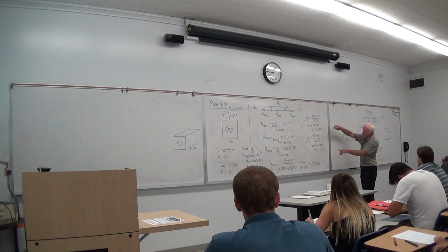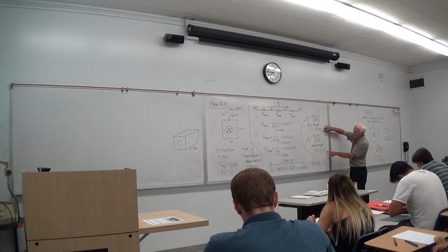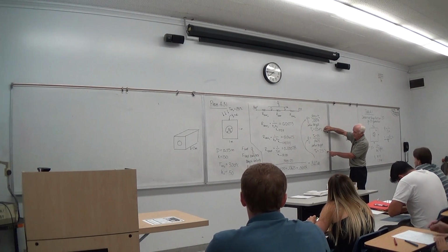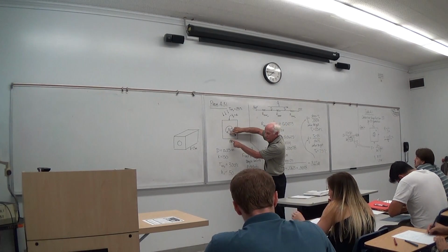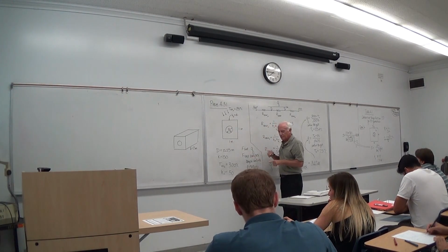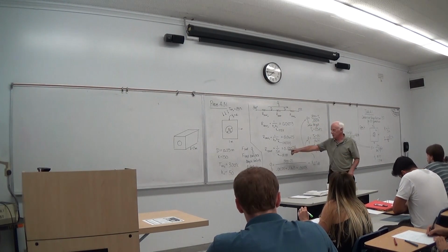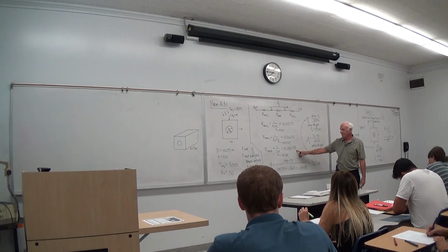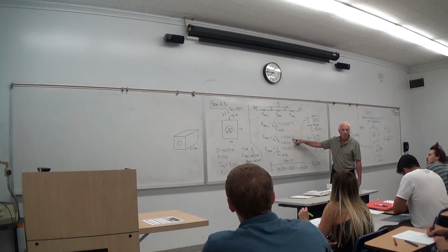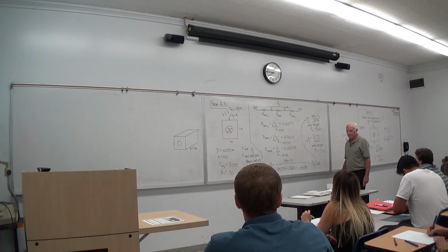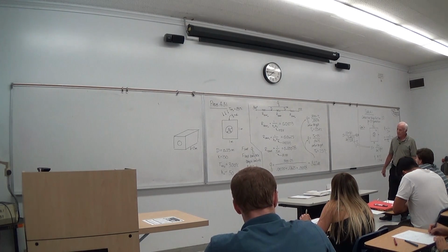Look how close those temperatures are to each other. At the inside of the material, the temperature is 254. The outside, 251. 254 here, 251 here. Not much change in temperature. It must mean the resistance is pretty low. We'll check conduction. Oh yeah, the resistance is pretty low. Compare this one to that one. 100 to 1. So yeah, there's not much temperature difference across that metal block.